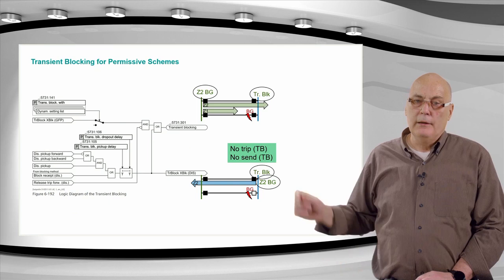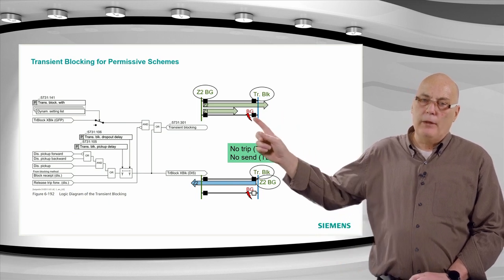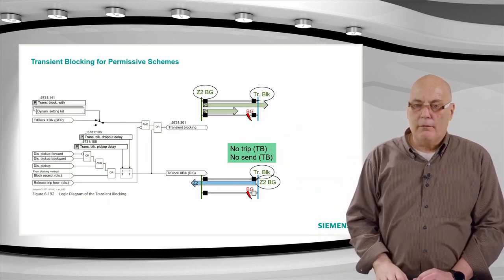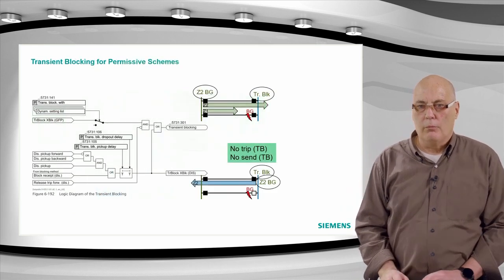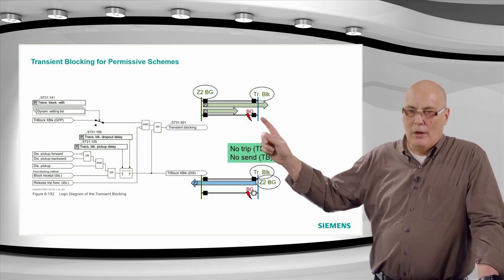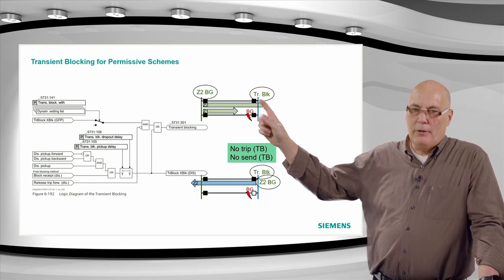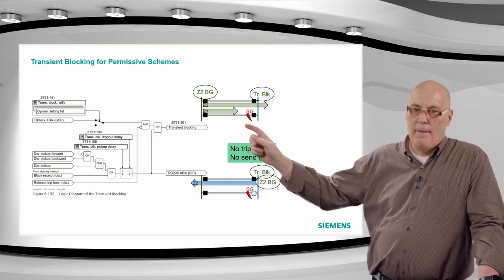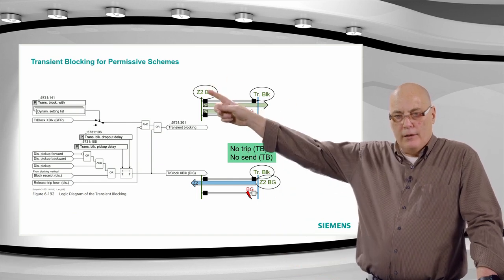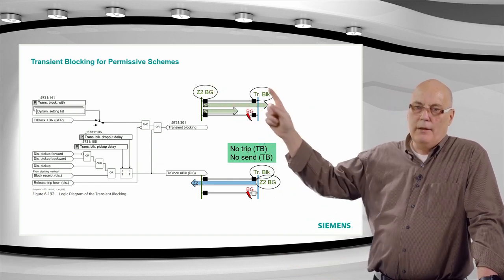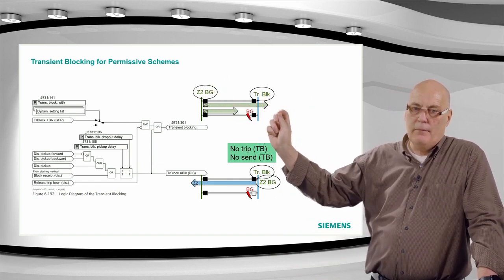So initially we have the top condition and we apply the fault here. I have to go through it one by one. So what happens initially, we will have a pickup on the right hand side reverse, and on the other side we'll have the zone 2B ground. So the left hand side at the top will be sending a signal. Here we will be receiving the signal, right?